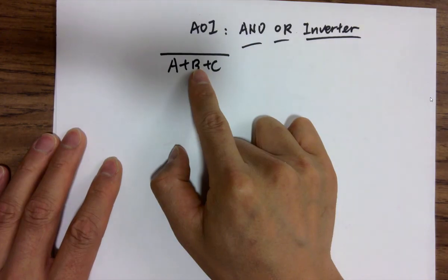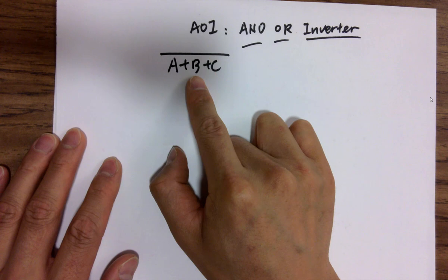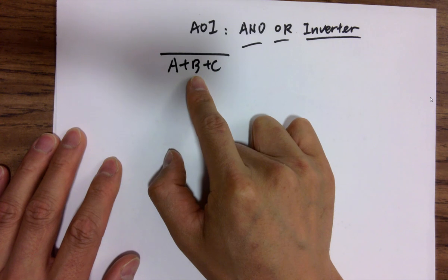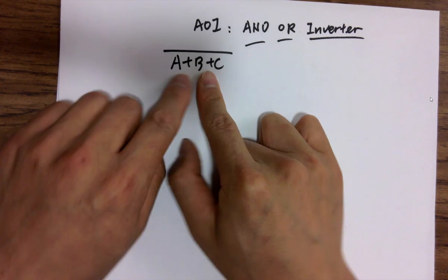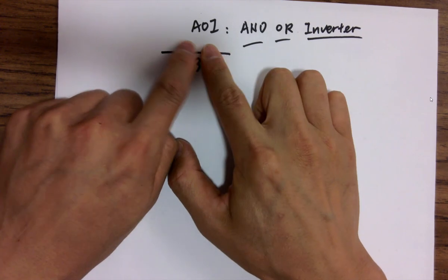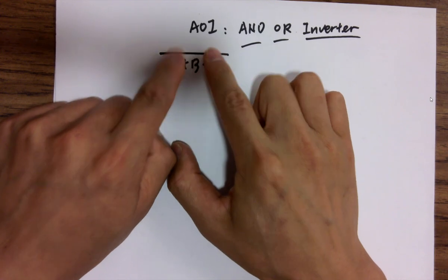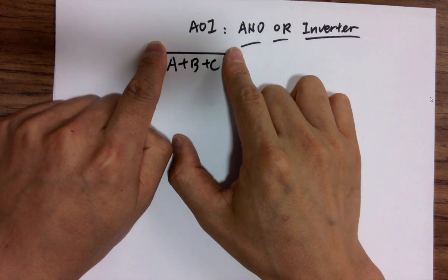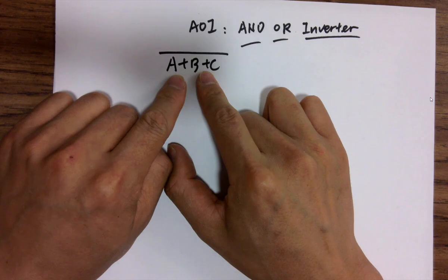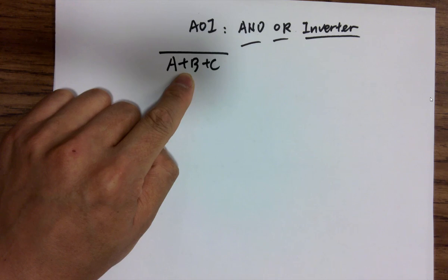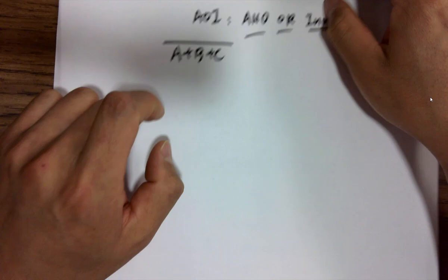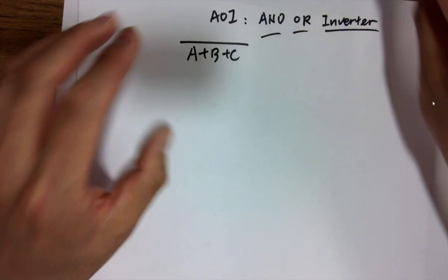So look at this one. Similar to what? The NOR gate. The only difference is you have one more input. So remember, for OR logic underneath a universal bar on the top, you need what? For the OR logic, you need a series PMOS on the top, and you need a parallel NMOS at the bottom. Are you getting that? So, yeah, we just have one more of each. Yeah, one more each. Why?